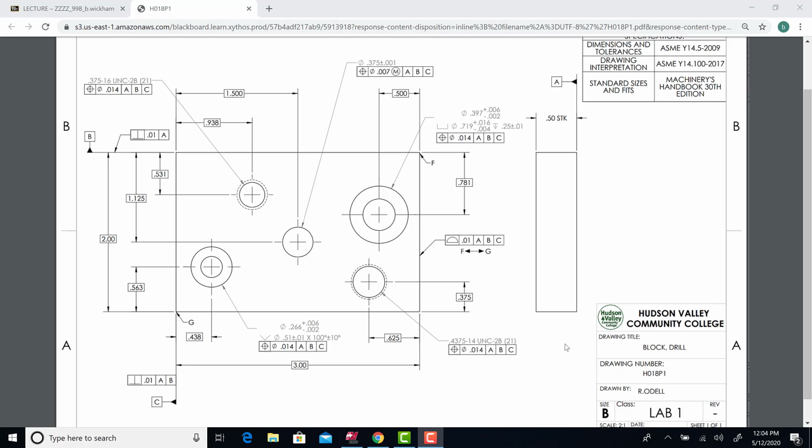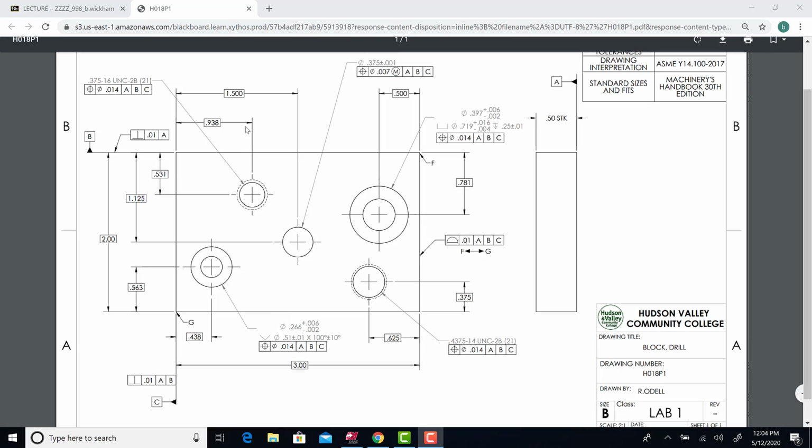All right, so for this final hole, the 7/16-14 class 2 thread, we are going to move our gnomon over to the lower right corner. We'll use some of the tools to move it at specific distances, in this case 3/8 in the Y and 5/8 in negative X. We're going to put the gnomon on the center of the hole to show you how to move the gnomon, and then we'll create this tapped hole as we would the upper one over here.